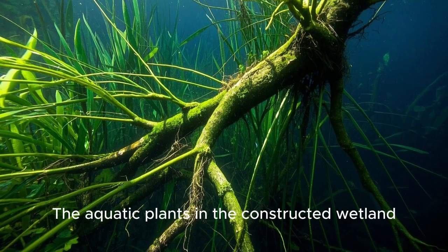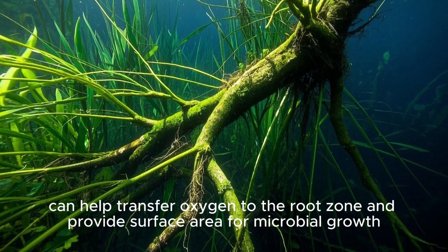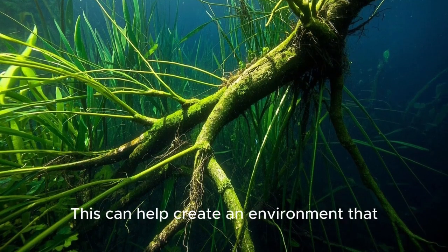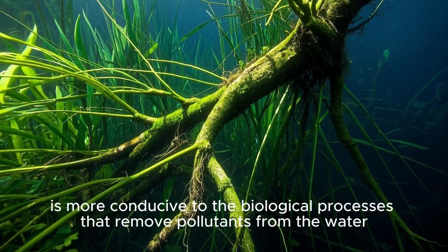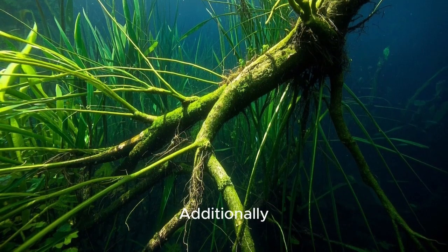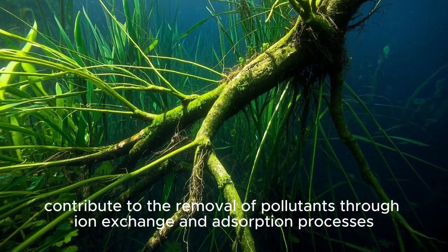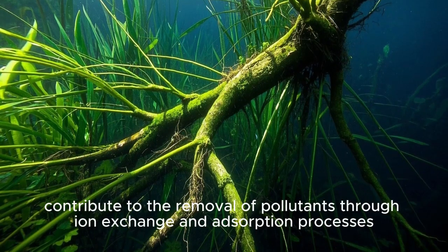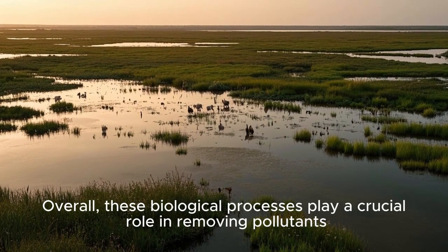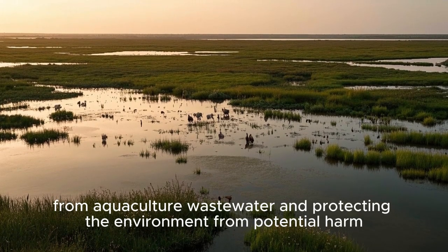The aquatic plants in the constructed wetland can help transfer oxygen to the root zone and provide surface area for microbial growth. This can help create an environment that is more conducive to the biological processes that remove pollutants from the water. Additionally, the roots of the plants can also contribute to the removal of pollutants through ion exchange and adsorption processes. Overall, these biological processes play a crucial role in removing pollutants from aquaculture wastewater and protecting the environment